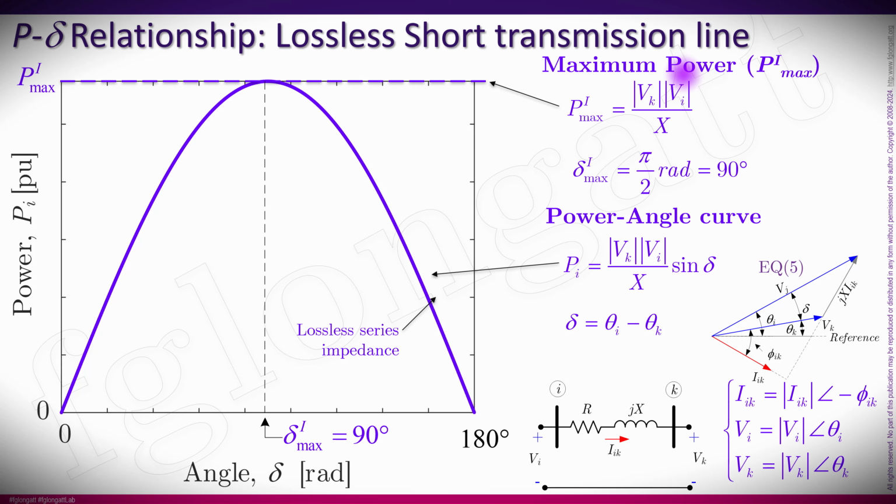However, in order to conclude this video, what I want to remind you is that this equation number 5 is defining the relationship between active power and the angle delta. Those voltages are steady-state AC quantities represented by phasors. So this purple line in the power angle representation defines the steady operating positions that are possible using the transmission line.